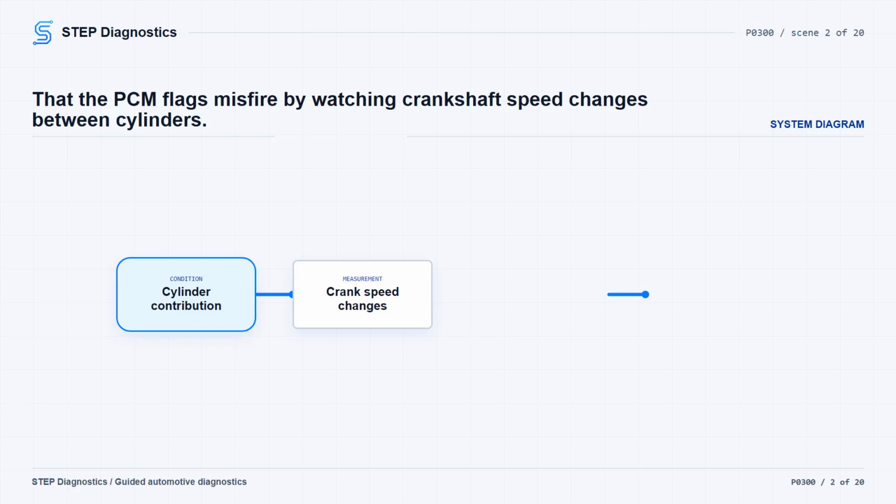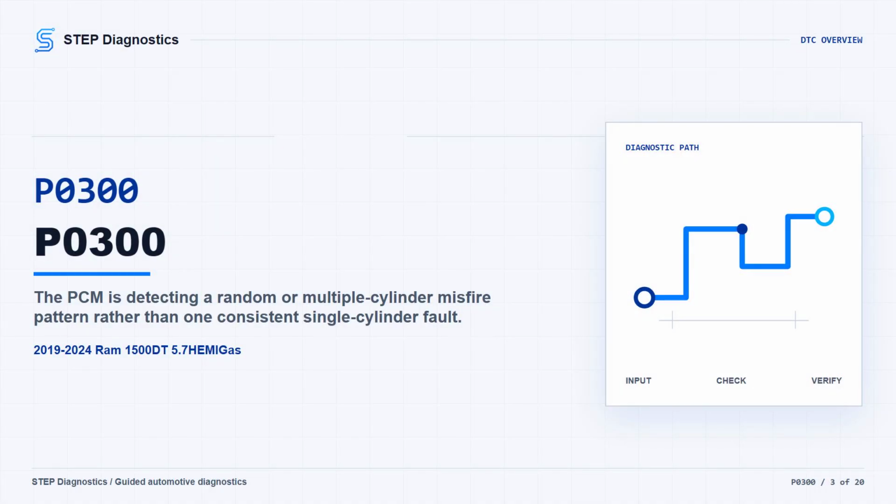Fuel level above 12%, battery voltage above 10.9 volts, ambient temperature above -23 degrees C, -9.4 degrees F, coolant temperature at engine start above -7 degrees C, 19.4 degrees F, or if it starts below that threshold, enable once engine temperature reaches 21 degrees C, 69.8 degrees F. Engine speed is between approximately 400 RPM and 6,200 RPM. The adaptive numerator has to be learned, and the monitor is disabled during a decel fuel shutoff event.